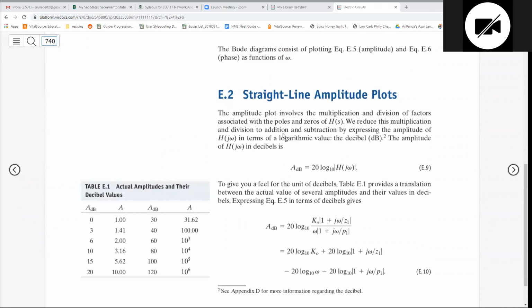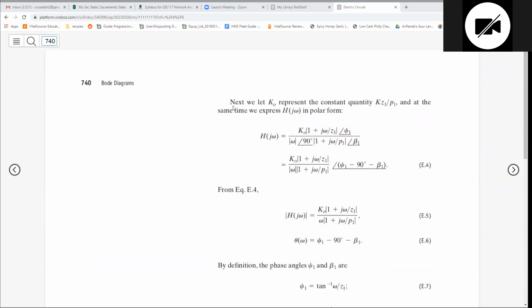So now we're going to go ahead and take that function and let's dice it up. Remember, there's 4 things. Let's go back up. There's 4 things in here, right? Or 3 things, sorry. We got our 4 things. We got our constant right here. So that's one factor we have to look at. We have a 0 up top. We have a pole on the bottom. And we have a second pole on the bottom. So there's 4 different quantities we have to look at.